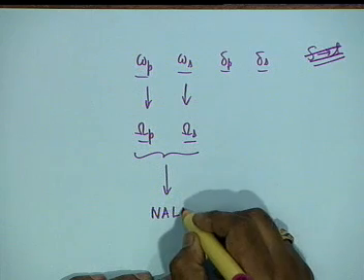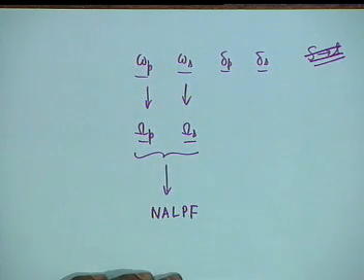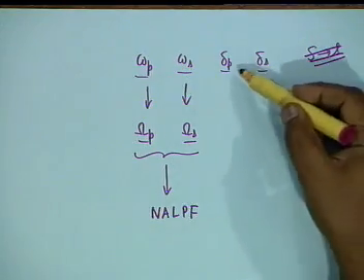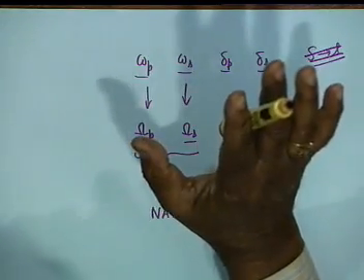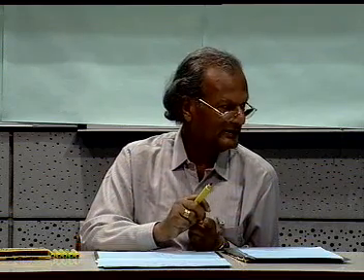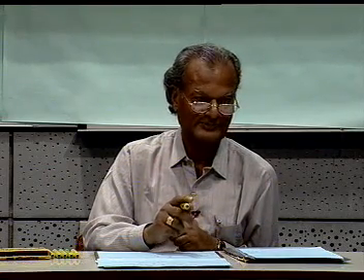In it, delta p and delta s are known, and omega p, the end of the pass band in the normalized filter, is 1. So all you have to find is the transition ratio, that is, omega s, the beginning of the stop band of the normalized filter.